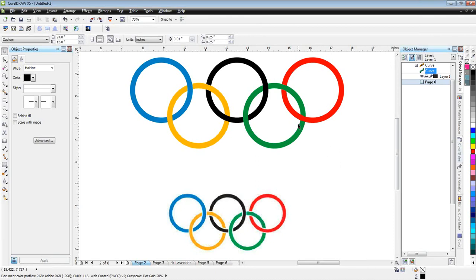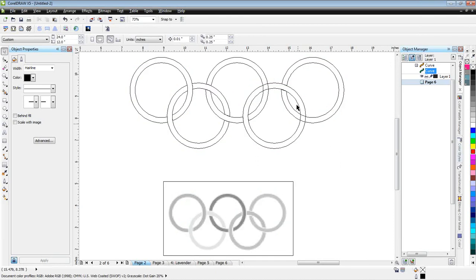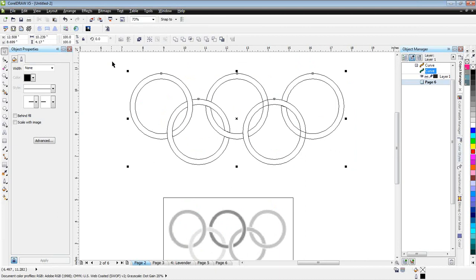Again, don't forget to simplify this. If we look at this in wireframe, I've got some lines going across, so I still need to take everything here and do the simplify tool, so it's kind of what you see is what you get, and it'll get rid of those lines in there. And of course, it's taken a couple seconds to think about that, and there we go.